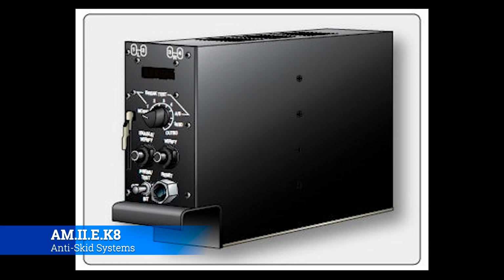Basically, this is the brains of the operation. Everything you see that's happening up top with the control panel talks directly to this box, and the skid wheel, or the wheel sensors, will be piped into this LRU, and we'll look at the hierarchy of how it talks to each other. But essentially, this box is looking at the speed at which those wheels are turning. It's programmed to say, hey, look, at certain circumstances, we're going to leverage the control valves and let some pressure off to prevent a skid.